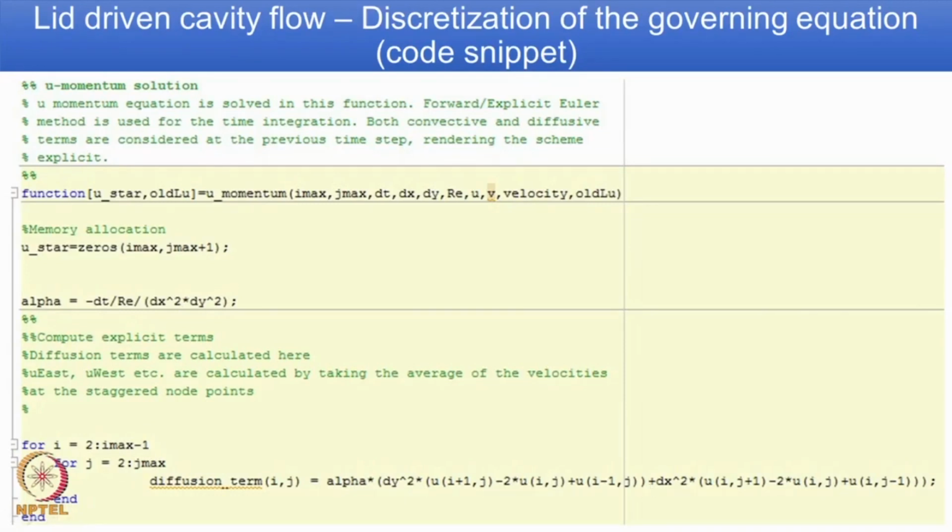Similarly, when you do the second derivative for the y direction, that is dou squared u by dou y squared, we have only delta y squared, we do not have a delta x squared, whereas alpha is generically defined considering both delta x squared and delta y squared. So, the extra delta x squared needs to be accounted properly.